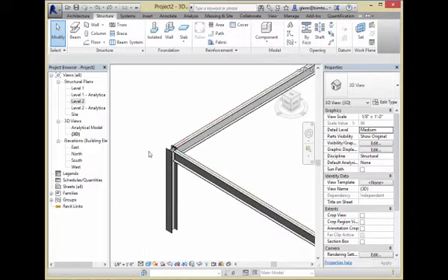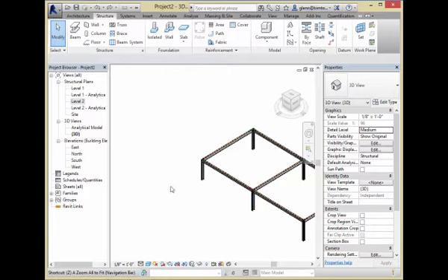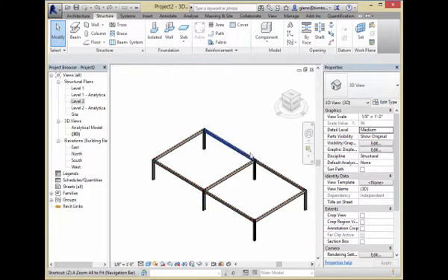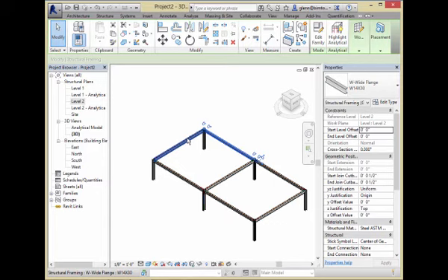Let me show you what I would do with that. I'm just going to grab all the beams. And as opposed to having them right at the floor level, I'm going to give them a little bit of an offset. It's called a Z offset. I'm just going to lower them down 5 inches. And why am I lowering them down that 5 inches? Because the concrete deck and steel is about 5 inches. So I'm going to put the beams underneath it. So I'll say lower that down.